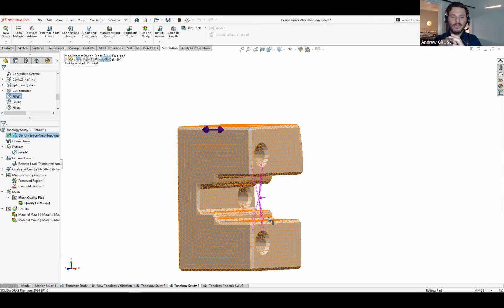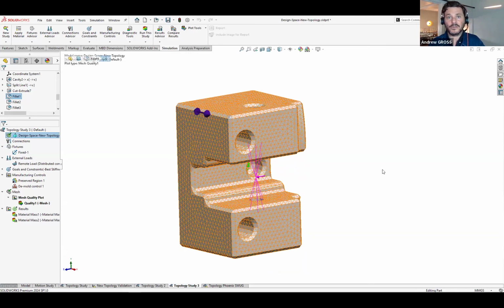an energy norm within this element. And at least probably we need to keep this, but let's keep trying. It's very iterative, and it keeps deleting elements until the energy pathway between force and fixture is all essential. It's a pretty cool technique. We borrowed this from one of our sister brands called Simulia, and Simulia makes the product Abaqus, which, not meaning to toot our own horn, is the most powerful FEA package on the planet.